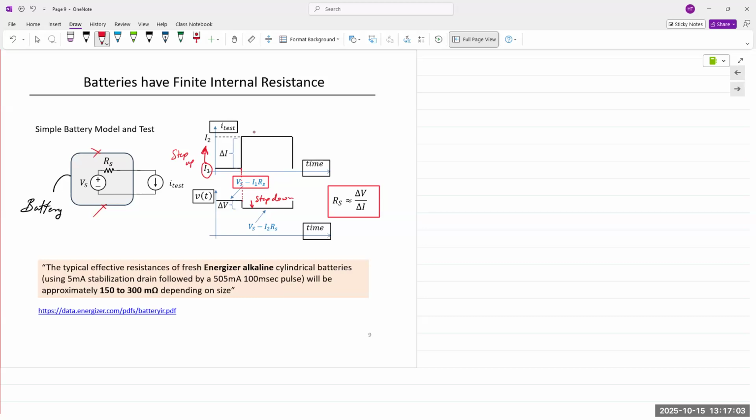Okay. So as batteries get older, the output voltage keeps dropping, and there are several reasons for that. One is this. Also, if you put too much of a load at the output, then the voltage will drop because it's going to cause more of a drop inside the battery, thus causing less voltage to appear at the output terminals.